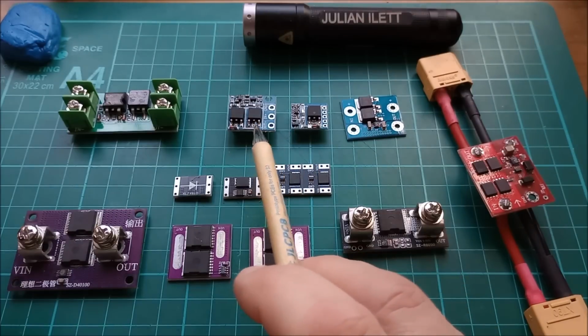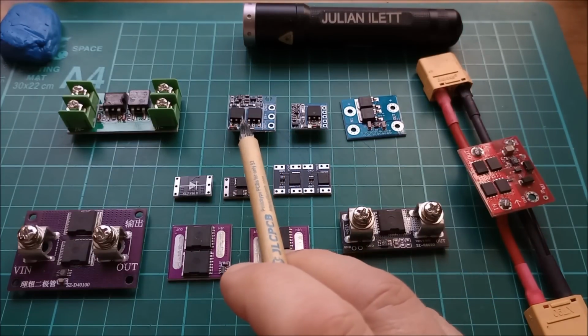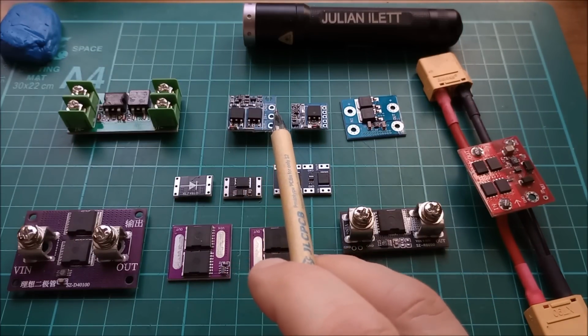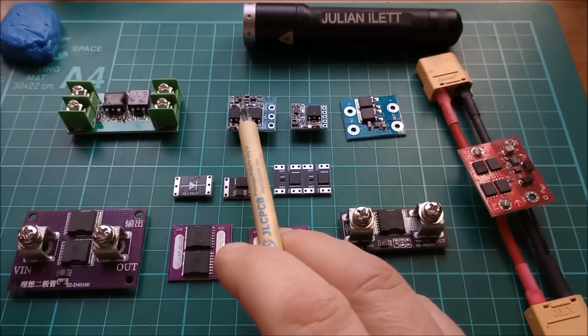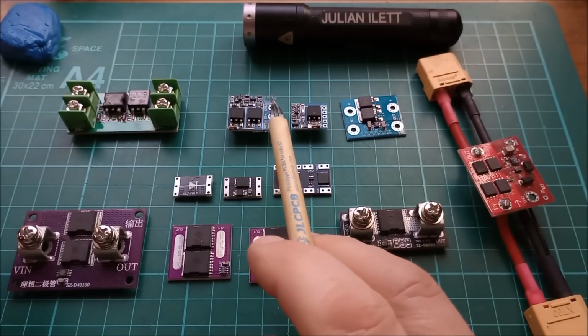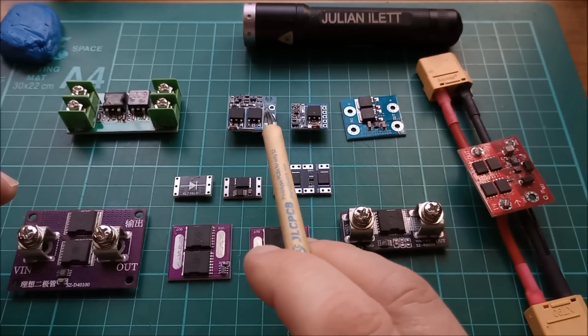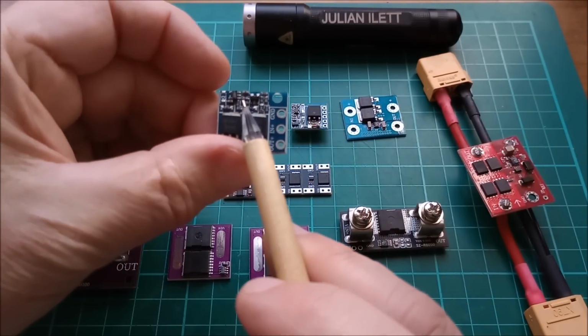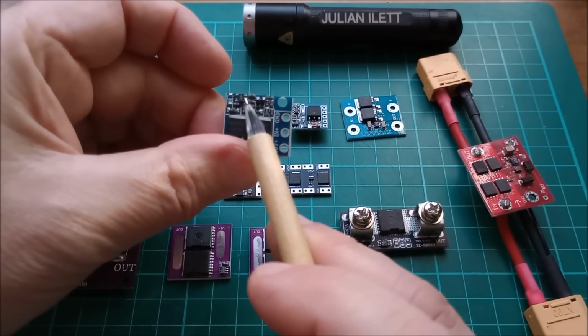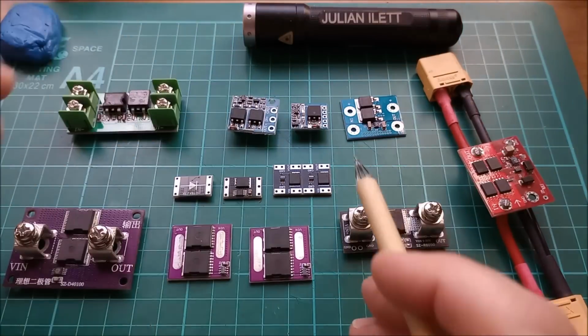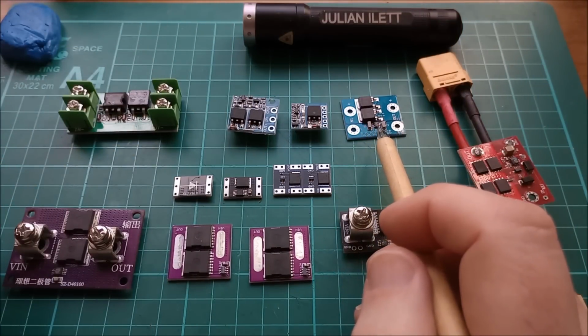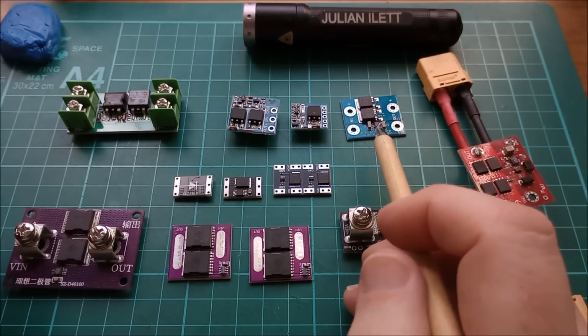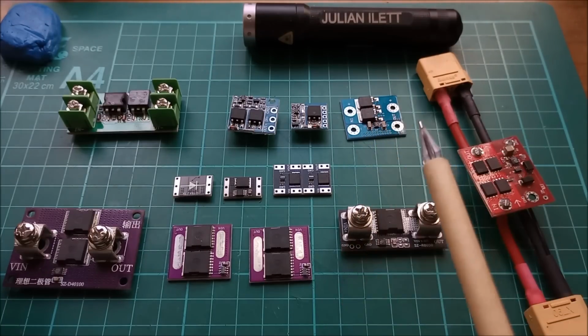And I believe these two here with the single MOSFET and the dual P-channel MOSFETs are all discrete apart from the MOSFETs. Well, they're discrete, aren't they? So these don't have an IC controller. There is a SOT23 5-pin chip there, but I believe it's just a dual transistor. This one here has a 6-pin chip and just 2 capacitors. This one I do believe is an ideal diode controller with P-channel MOSFETs.